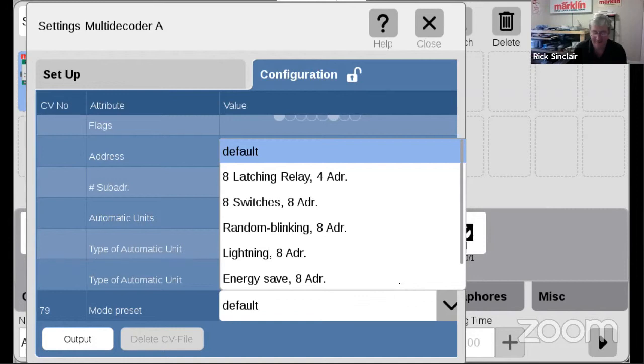So it kind of acts like an M84, I would think. Yes, they're both configurable the same, except the M84 does not draw track power to these accessories. An M83 will take track power from these accessories. So if you're trying to light a building, use an M84 because you're not stealing your own track power.